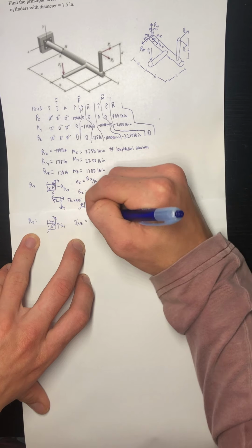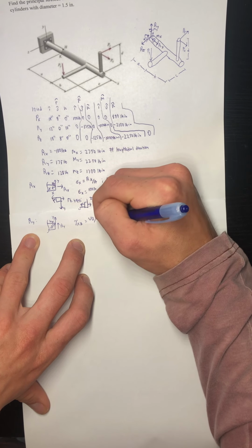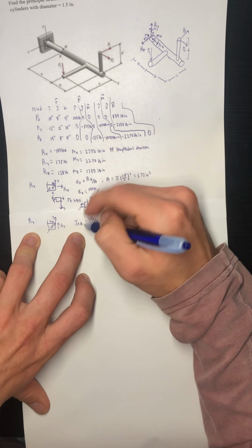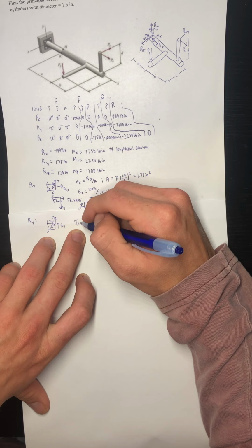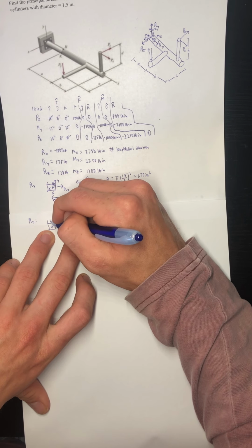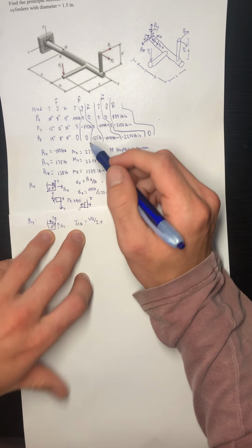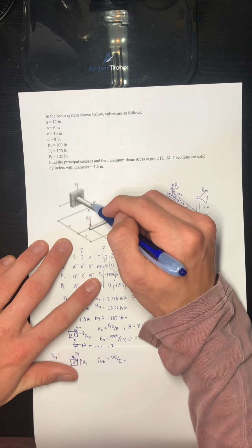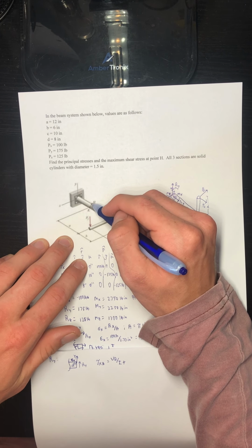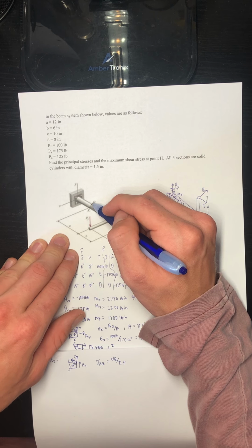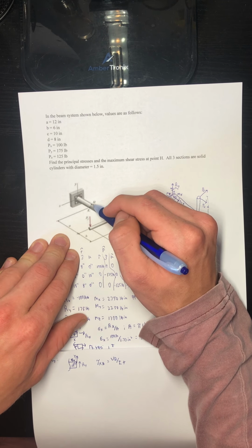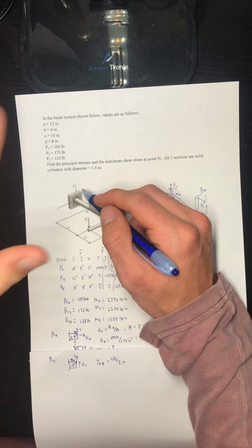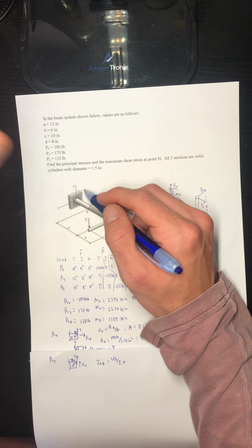Okay, so our transverse shear, tau xz is equal to VQ over It. So our shear is going to be acting in the XZ direction because our little differential H exists in the XZ direction. So it's sitting on the top of this, and that means if you look at the little square that it would be, it extends in the Z direction and the X direction, and it's essentially lying perpendicular to that Y axis.